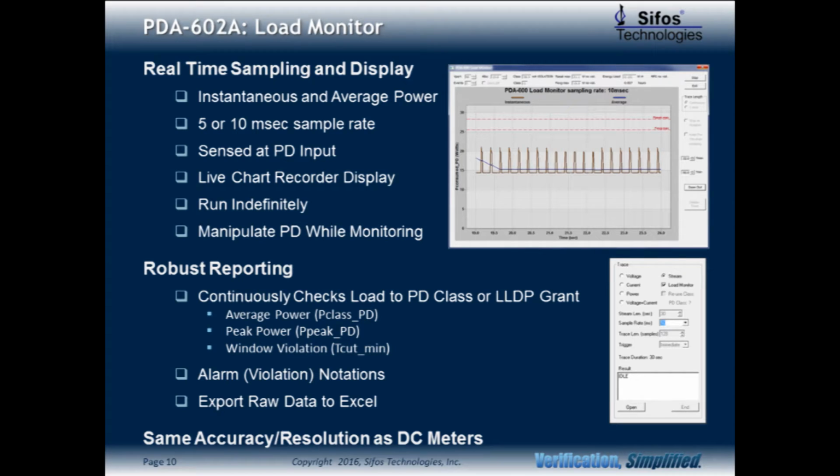For many PDs, full PD conformance testing cannot be achieved with the PD conformance test alone. PDs that present varying load conditions depending upon operational states, interface conditions, and network controls must be analyzed over periods of time where all of those conditions are exercised. Both steady-state power draw and load transients must be continuously observed to assure that the PD does not create a condition that might cause a PSE to remove power.